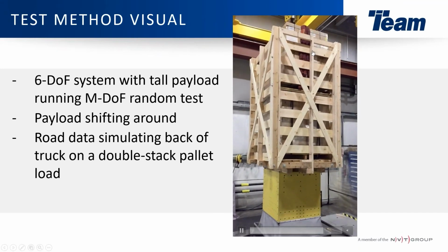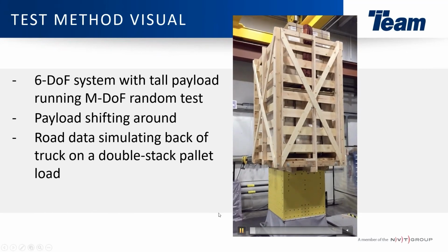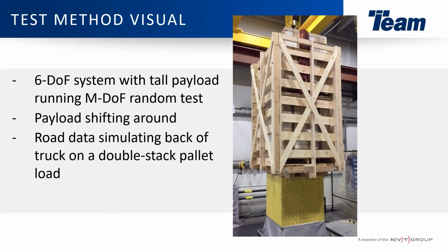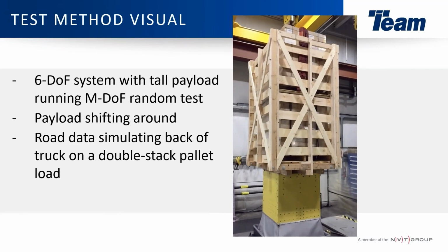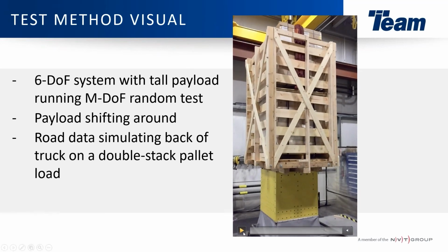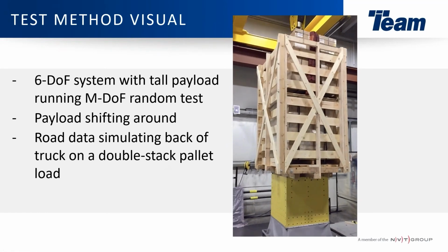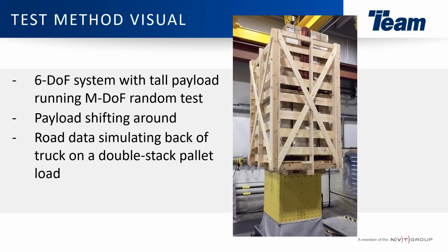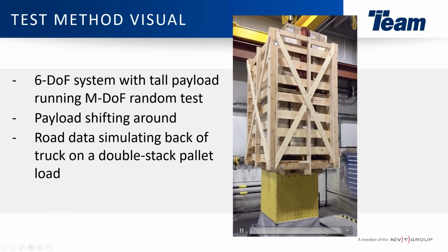adding on a more realistic representation. So again, specific to the package industry, most containers or most trucks, when they're shipping products, will put either one pallet on the bottom or add a second pallet on top. By doing that, the one on top, as you can see here, is seeing much more displacement. We didn't have any accelerometers to measure what the displacement accelerations are up at the top, but you can visually see that it's quite strenuous up there.